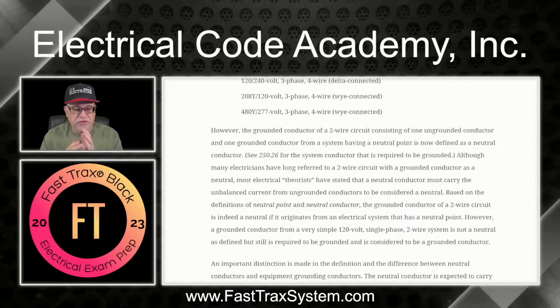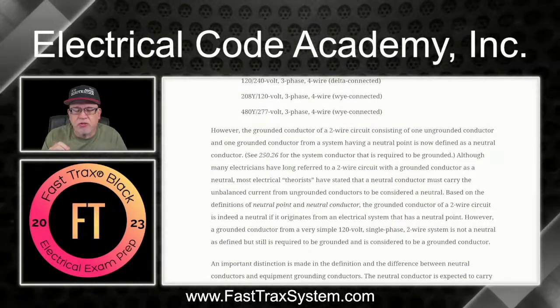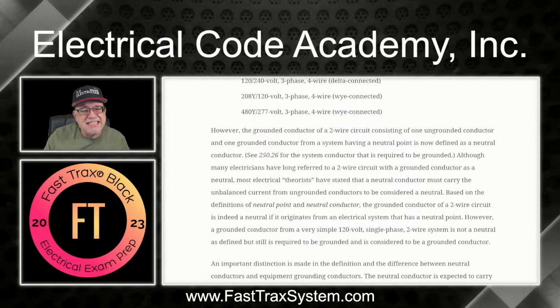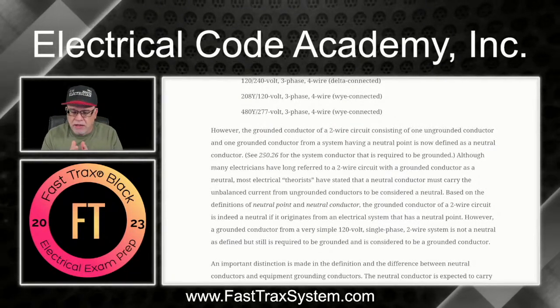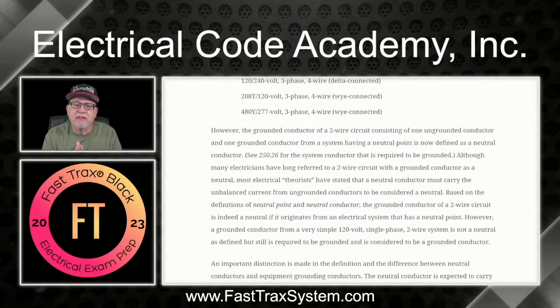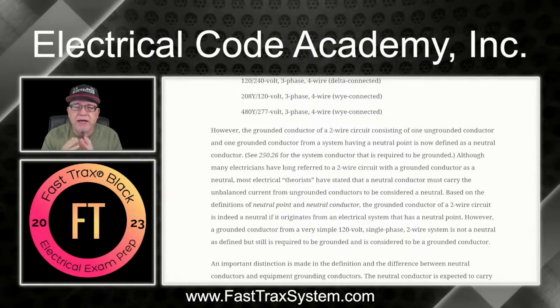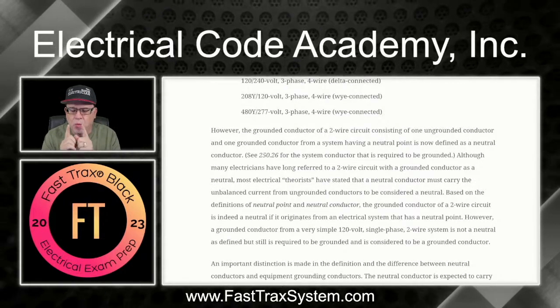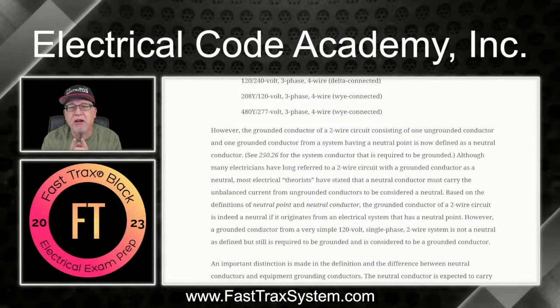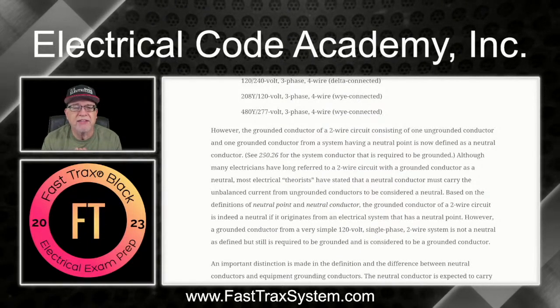Now, discussion. I'm going to get a little bit into the difference between theorists and what the NEC says. In 2008, when they came up with the definition of neutral and added neutral point, it started to take the theorists, who said, wait a minute, if I have a black and a white in a non-metallic sheath cable, the white wire, if we understand the neutral, is to carry the unbalanced load.